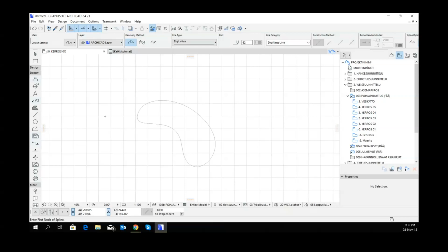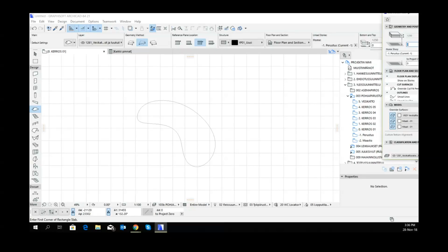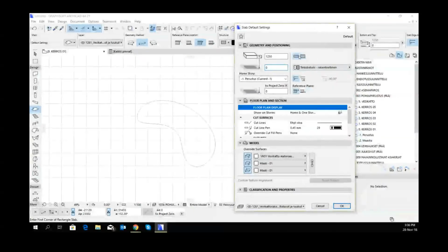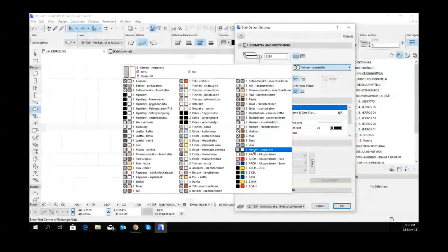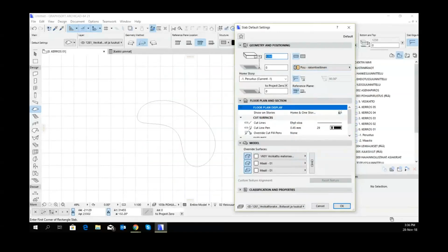And so now this is how we want the top to look. So now we're going to make the table just as though we were building an object or a building or whatever. So, oops, that's over here. Grab the slab tool for making the top. Choose a material. Make it wooden. Set a thickness, so if we say it's going to be, say, 25 mils thick, and a height, so we want it to be, say, 600 from the ground to the top.